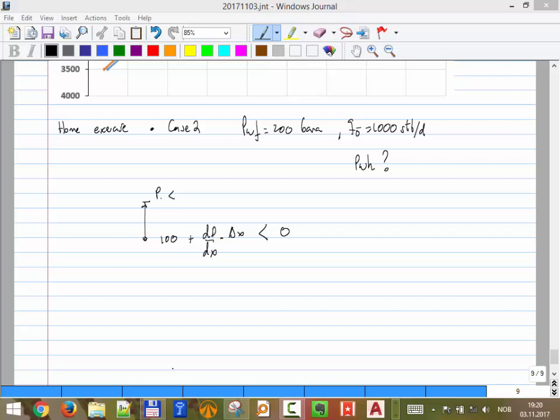Then we went for the case of gas, and we really went in detail for gas. We covered everything: the tubing equation, and we calculated pressure along the tubing. We also talked a bit about IPR, and what else? Oh, choke. If the ratio between downstream pressure and upstream pressure is less than half, more or less, as a rule of thumb,